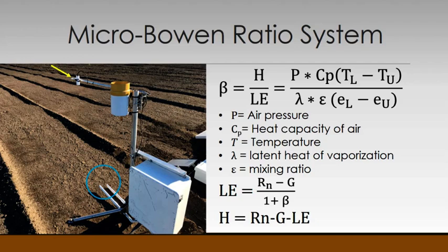And so we actually decided to wait until after a substantial rainfall event occurred to cause some compaction of that loosened soil. While it was wet and a little bit more compacted, it made it an easier task. We were fortunate that, during a pretty dry summer, a rainfall event occurred, I think 2 or 3 days following our tillage.